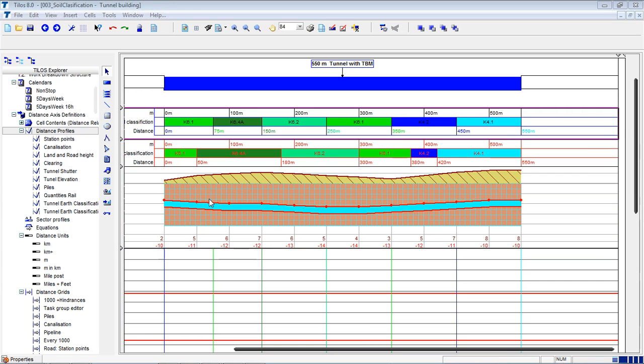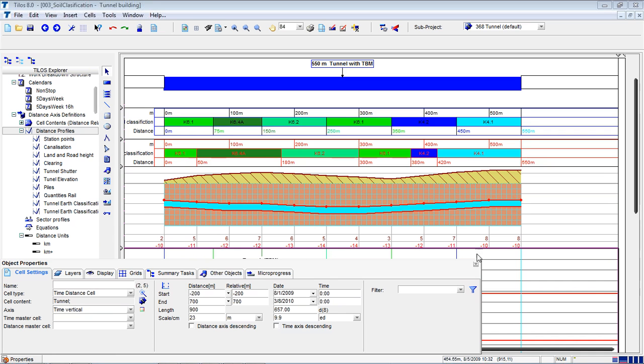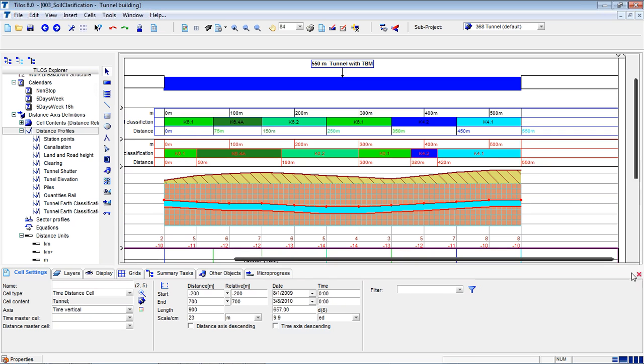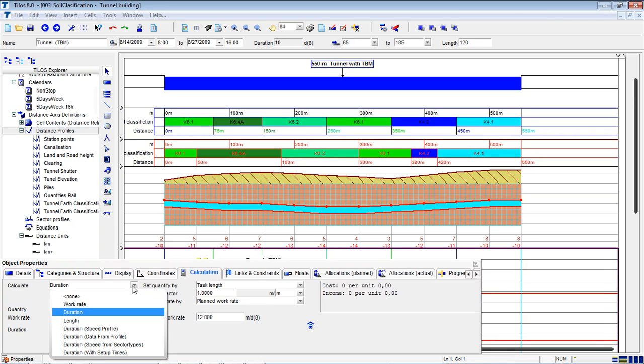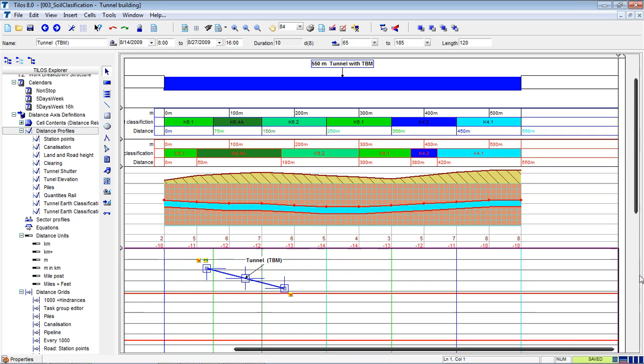Another question from Ivana. Yes, Ivana, I think that I answered it. When I enter the activity, just a simple activity here, I go to calculation of this activity. Of course, I need to select the activity first. I go to calculation of activities, and from here I select duration from the time, duration from the location, and I select which profile is calculating which activity.